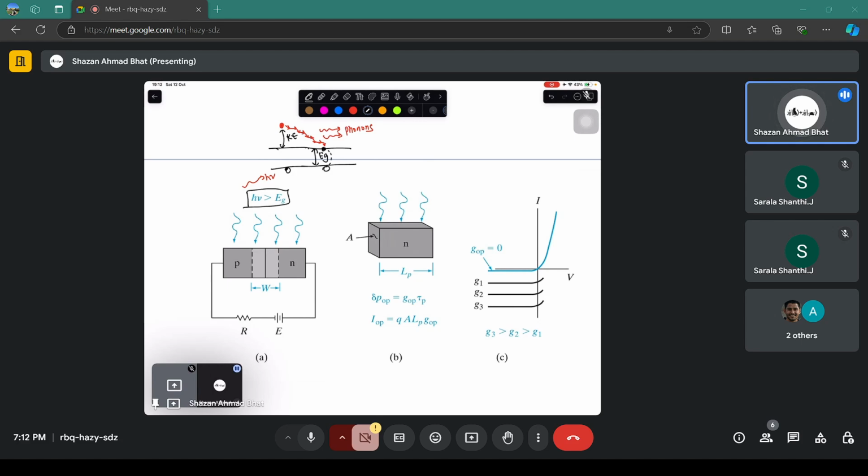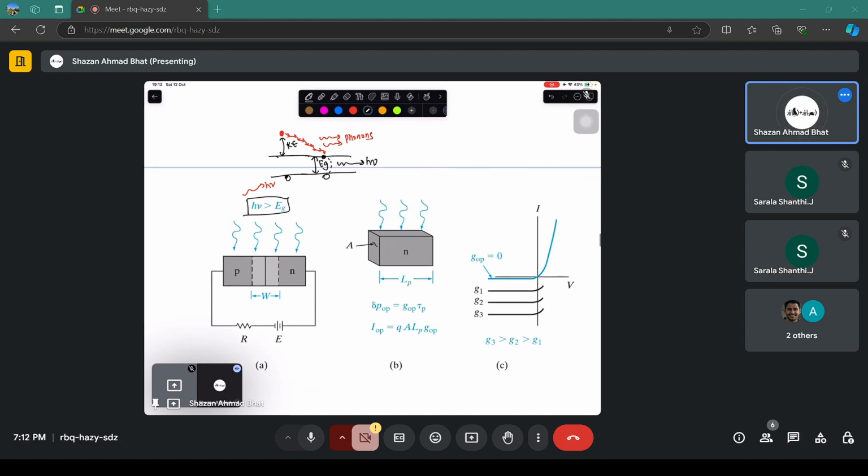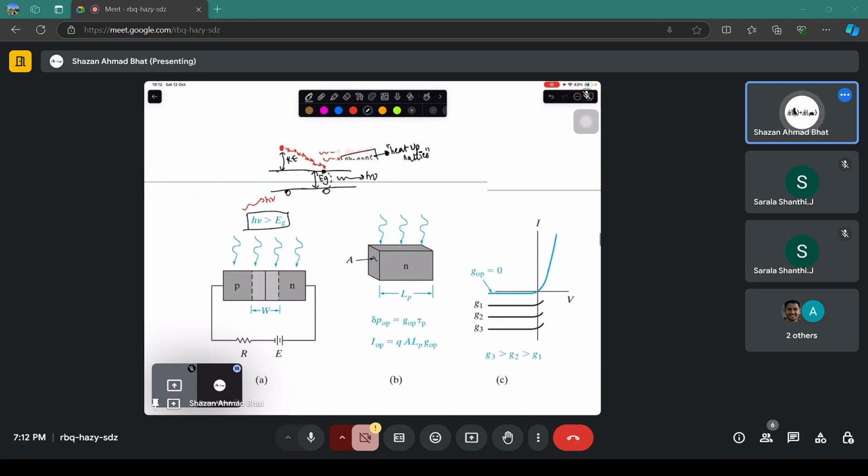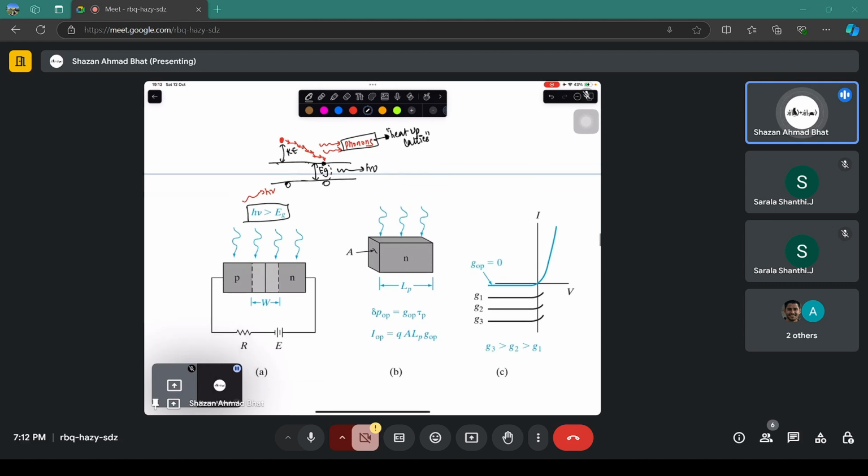the electron can go and recombine with the hole, then it can give off the photon again. Okay, that is the exact scenario of what happens. The electron's excess kinetic energy gets converted into other quasi-particles, which are the phonons, and these phonons heat up the lattice. Well, not all phonons are bad, but some phonons heat up the lattice, but I don't want to talk about which phonons are good and bad. But they give rise to the lattice heating.